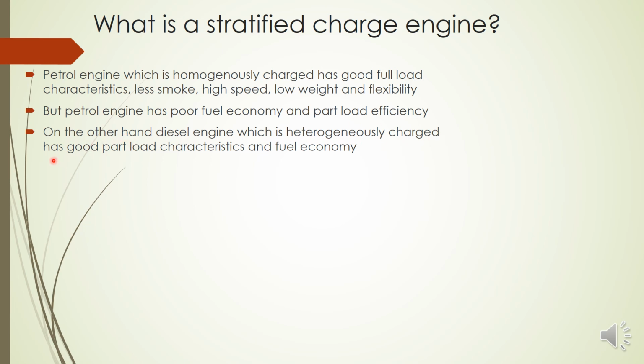And it has several advantages also: good part load characteristics, good mileage, that is fuel economy. But it has the disadvantages of more weight, more emission of smoke, poor air utilization, etc. So these things we already know. Then the stratified charge engine is an attempt to combine the advantages of petrol engine and diesel engine. So this concept arises like that.